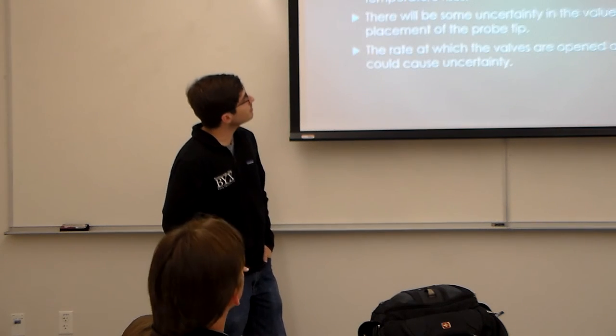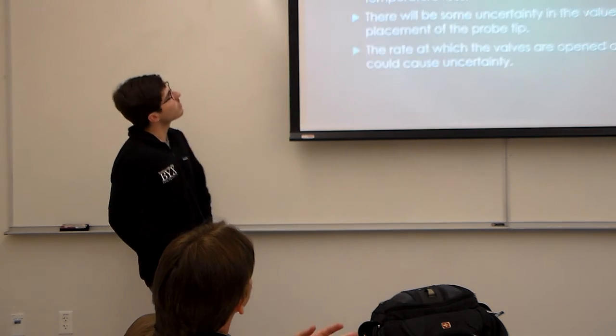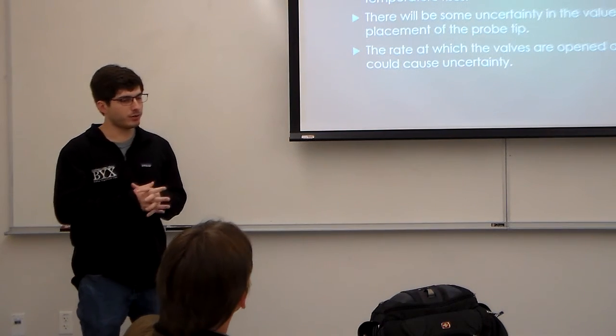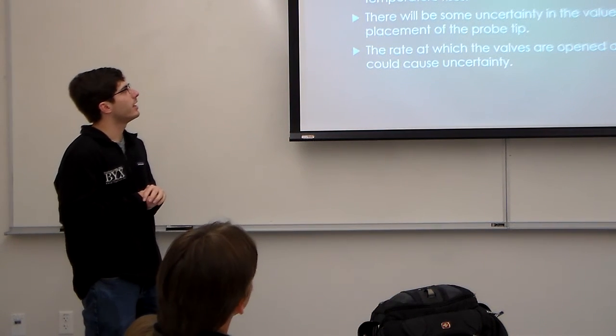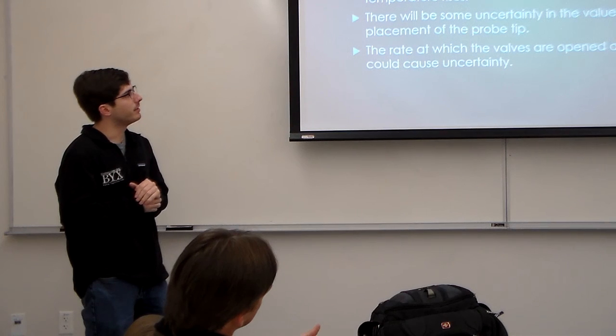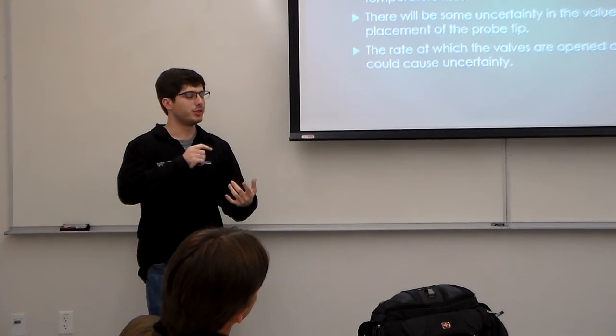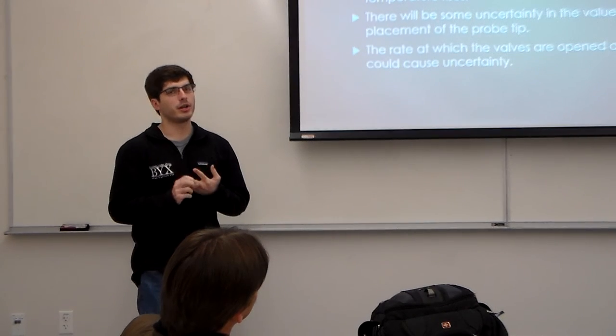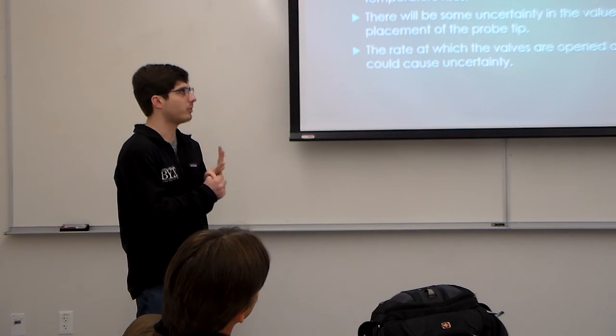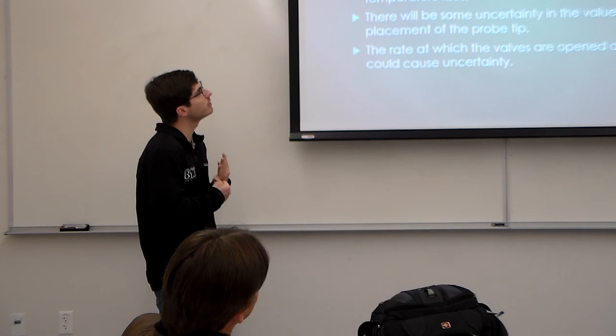Next slide. Our expected results will follow the standard relationship of our PVT, and the latent heat of vaporization should decrease as temperature rises. There may be uncertainty due to, as mentioned before, the thermocouple tip, human error, instrumentation error, and also how we treat the opening and closing of valves.